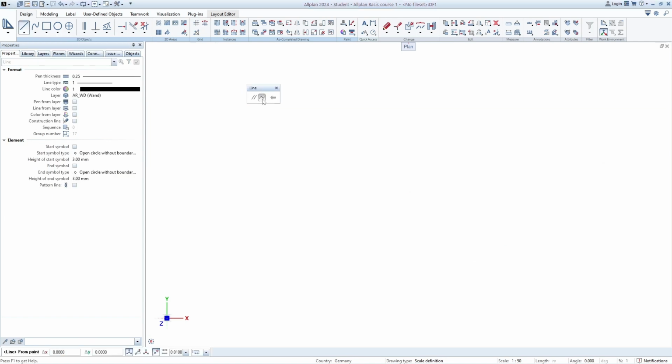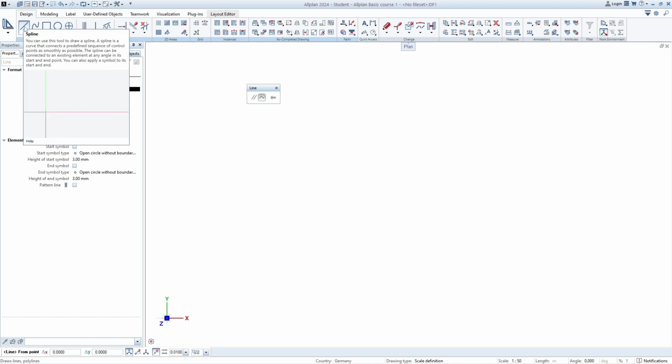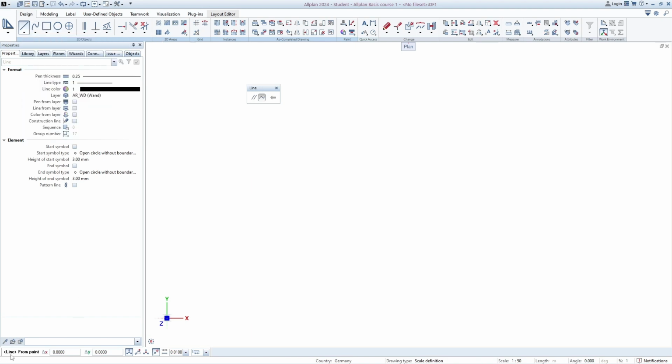So let's go together online. We have the polyline activated, and now we will start with our first construction in Allplan itself. So let's take a look at our dialog line. As I told you earlier, you activate one kind of option, and after that you always look at the dialog line to see what kind of input is expected from you.